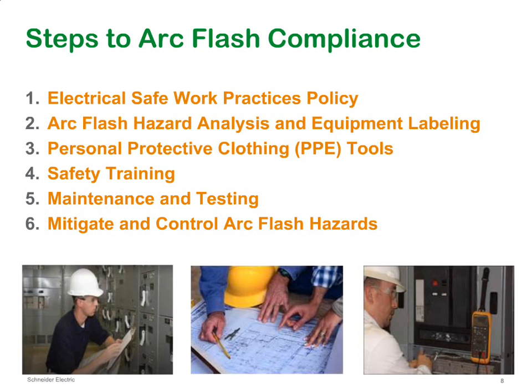So what are the steps to compliance? Not just arc flash compliance, generally compliance to the National Fire Protection Association requirements and the Occupational Safety and Health Administration requirements. You have to start with an electrical safe work practices policy. So the policy of the company, it's really an EHS policy. This is the EHS department that establishes this. So it's a responsibility of the corporation to have a written policy that outlines what the responsibilities of the facility owner are and what the responsibilities of the worker are. So these need to be clearly defined.